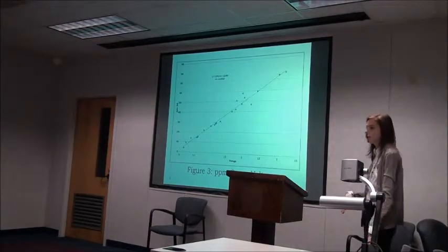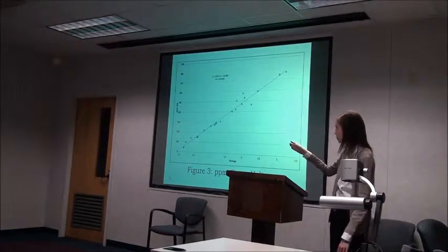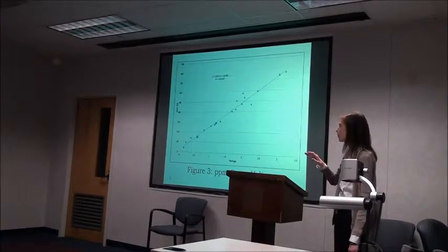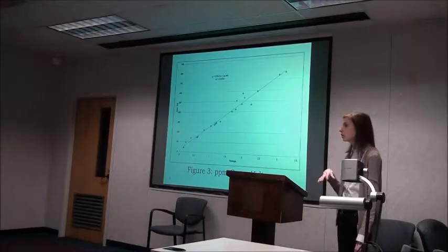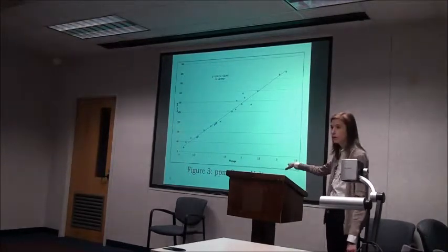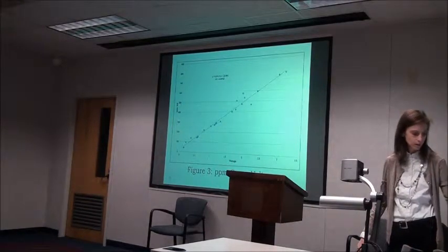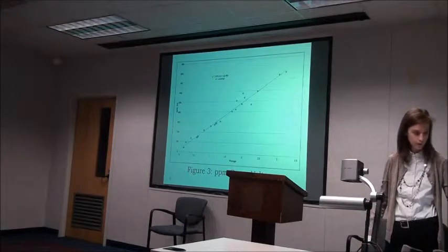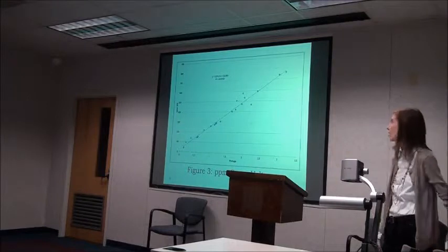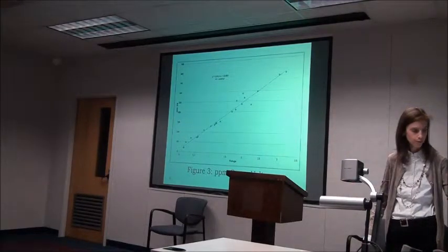So as I previously mentioned, this is just showing the calibration where we have parts per million O2 versus the voltage, and these parts per million was what I hand recorded during each trial to correspond with the voltage reading given by the data logger on the x-axis, excuse me. And you can see the equation here. I fit that equation and use that to convert all of our values.